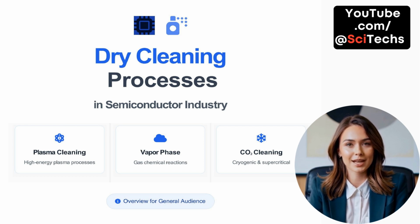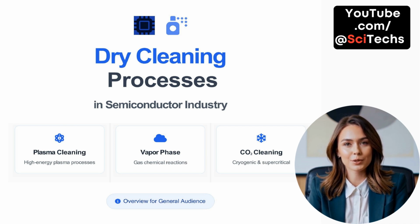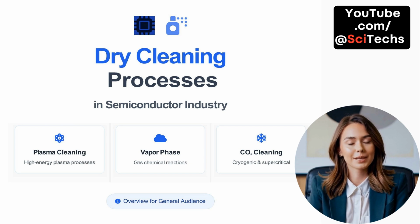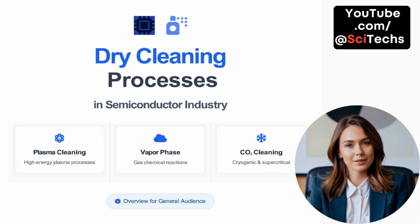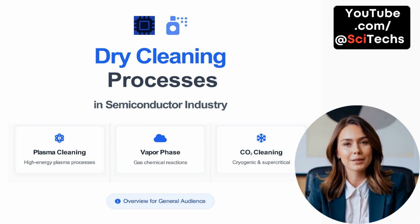CO2 cleaning uses either cryogenic or supercritical carbon dioxide to lift away particles and residues gently, making it suitable for fragile structures. Together, these dry cleaning techniques support high yield, process integration, and cleaner semiconductor manufacturing environments.